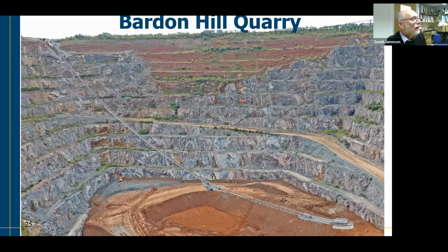And the most efficient way of removing it is to take it via conveyor out of the old quarry and to the head of the corner here, where the conveyor will deposit material onto the rope conveyor, and that material will then be deposited into the bottom of the quarry. But with the rope conveyor, of course, you have a certain amount of bend in the whole structure to allow it to deposit materials at the bottom, and then as the bottom of the quarry fills up, that is pulled up coincident with the rising level of the waste.